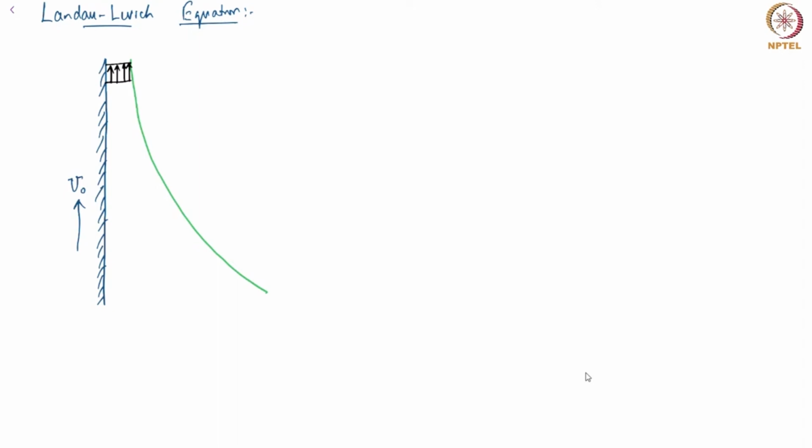Okay. So if the thickness of the coating is h infinity, then we know that the mass flux going through the coating would be u0 h infinity times rho. This is mass flux per unit depth. Okay, this is a two-dimensional problem, mass flux per unit depth.